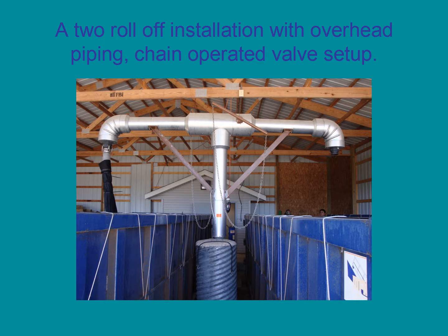Many new plants are being designed with multiple roll-off dewatering pads and piping systems that save steps for the operator. This plant has a 2 roll-off installation with overhead loading for the bags. Chain-operated valves on the horizontal legs allow the operator to switch filling between the bags.